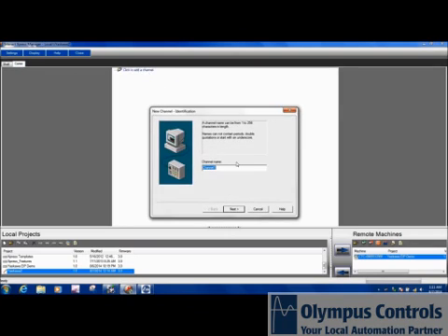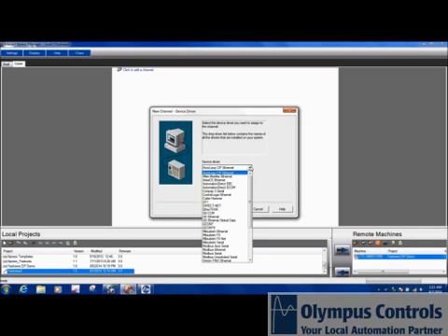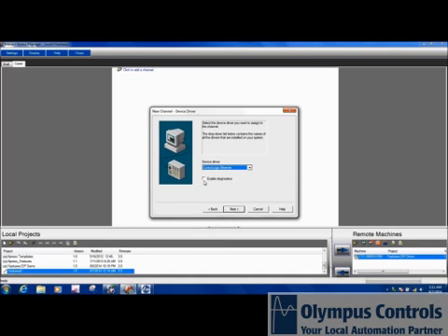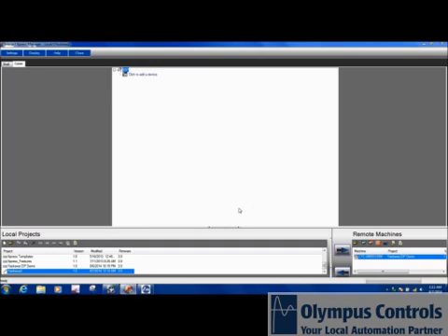We add a channel. You can think of a channel as a network, whether that's Ethernet, EtherCAT, Ethernet IP, Modbus TCP. Just going to call this one EIP for Ethernet IP. The device driver we want to use is the CompactLogix Ethernet driver. We want to enable diagnostics, and then we'll go back here. The network adapter, I like to specifically select my wired network adapter that is connected to this PLC, and then accept the default settings. Click Finish.